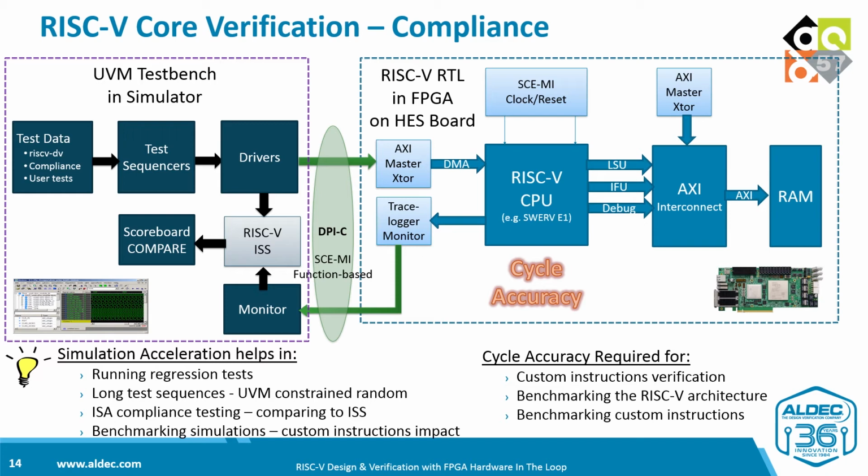In our example, a standard AXI master transactor and a custom-made trace monitor are based on the Accellera SCE-MI function-based interface and integrate very well with SystemVerilog UVM through DPI-C. And by using SCE-MI, we achieve interoperability of the UVM test bench, which now can be used either with the design simulated or emulated in the HES FPGA board.